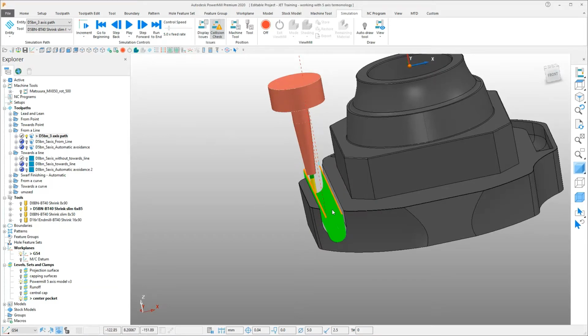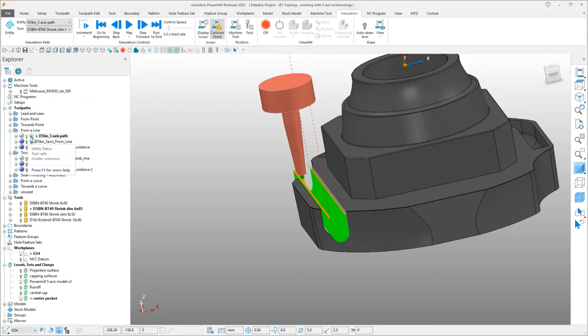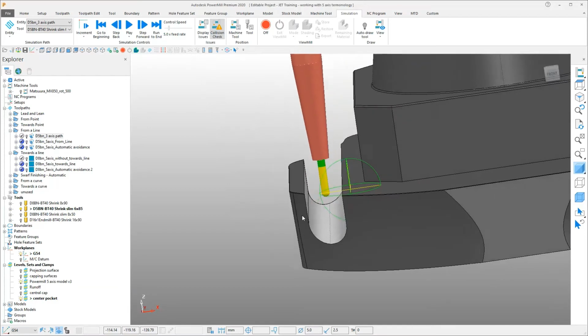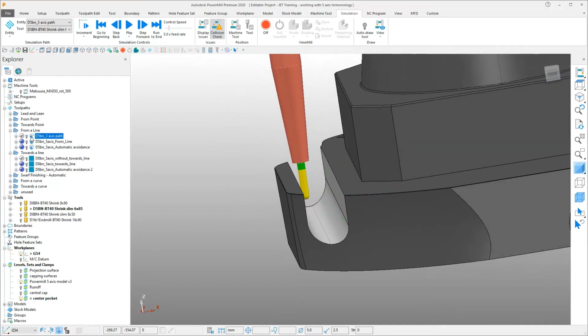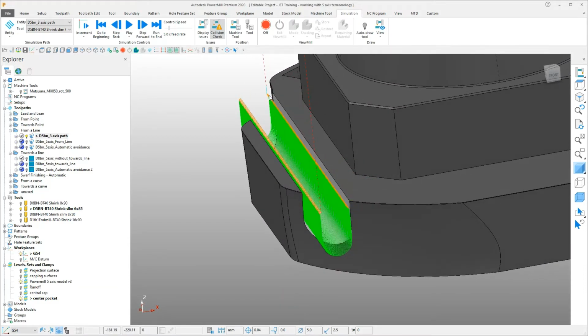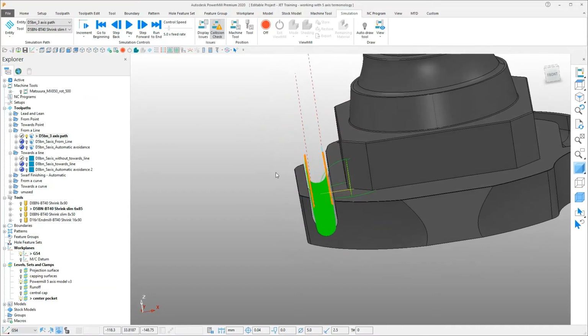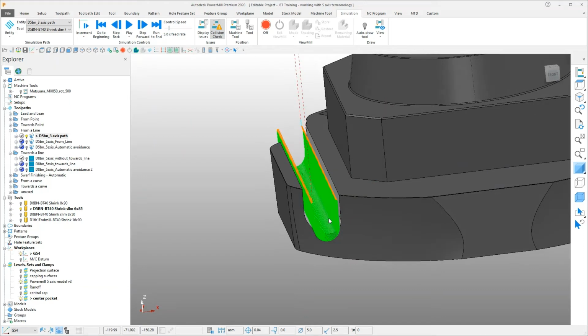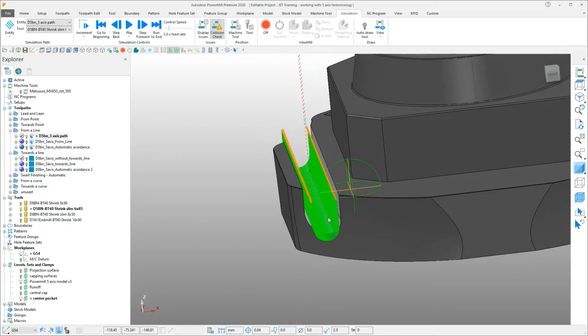So we have this standard 3-axis toolpath here, and what this is going to do is machine through that highlighted slot cavity through the component. Using this standard 3-axis toolpath, I'm just asking the tool to trace up and down the wall and move along through the slot, for the purposes of demonstrating this strategy of programming from a line and how that can benefit you in this type of feature.